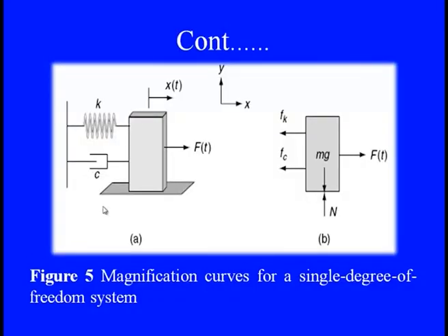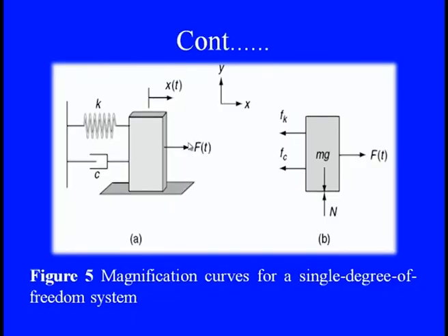So, when we look at this, we can see the forcing function F of t equals F0 sin omega t. This is my forcing frequency, which supplies the force or the energy at a certain frequency. And when the entire system with the mass, stiffness and damping is excited, then we see what exactly the exciting features from this machine are. So, we have the system's inherent frequency, the exciting frequency and the forcing frequency.